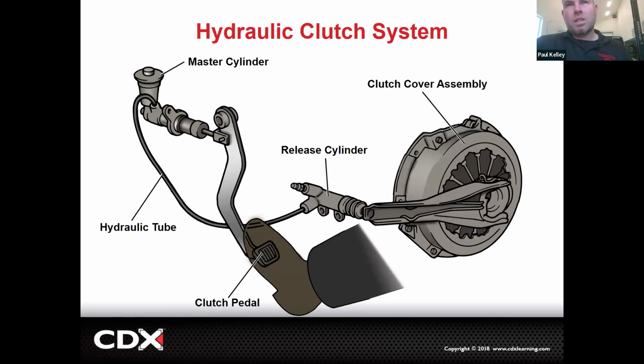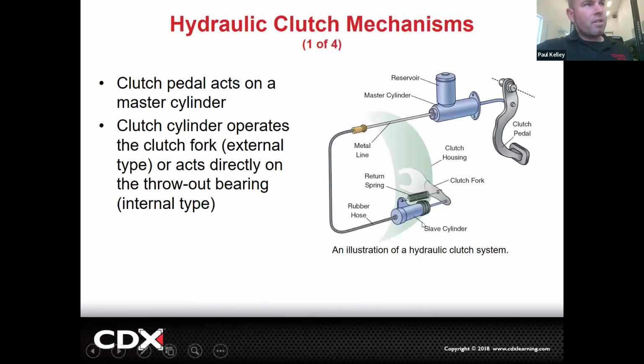They could have some internal leak too, but they could also have a leak where it actually pukes the fluid out the push rod, and this is inside the car, so the brake fluid gets on your toes. It's pretty much how it works. Cool, that would be clutch master. Would it be the slave? No. If a slave is leaking, it might look like it in this picture, but that's outside the car. It doesn't drip on your toes, right? That's down here. A slave cylinder would drip on the ground. A clutch master might drip inside the car if the seals are bad. Cool.